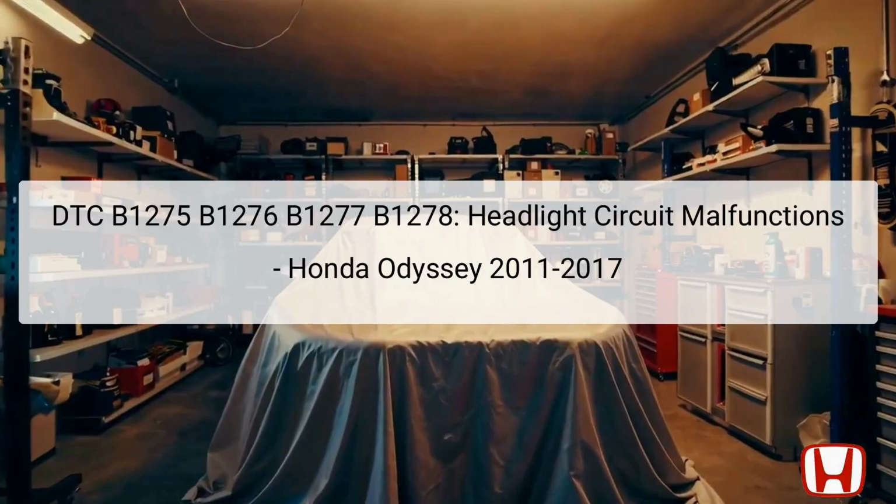This presentation covers the diagnostic trouble codes DTC B1275, B1276, B1277, and B1278, which relate to various malfunctions in the headlight switch circuit for the Honda Odyssey models from 2011 to 2017. Each of these codes indicates a specific malfunction concerning the headlight switch positions, namely off, parking, auto, and on.